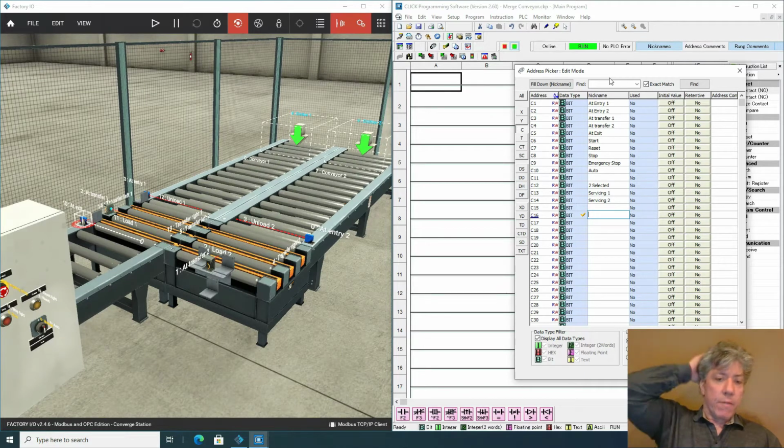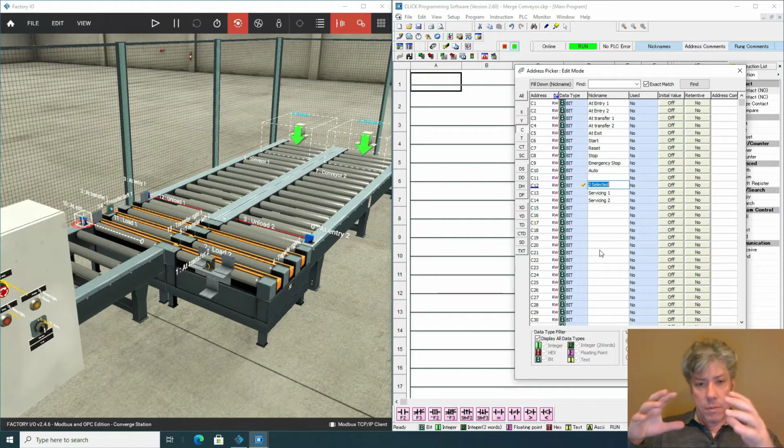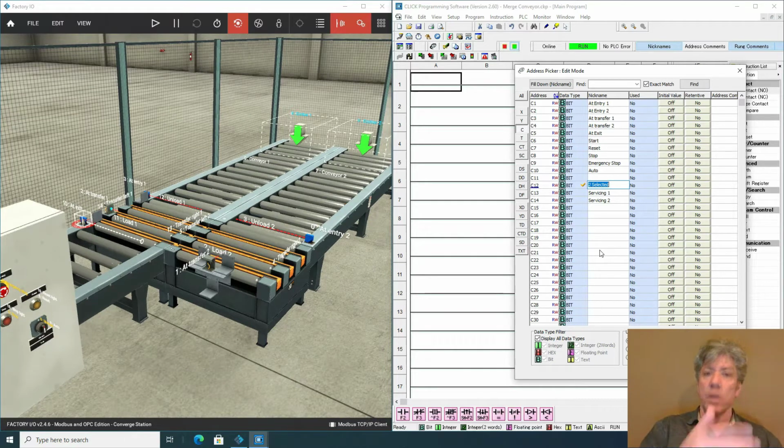Well, to make it fair, you know, it's possible that there could be continuously something that keeps appearing where I've got pallets just waiting to be merged together, and so I've got to make a decision. So what I've done is I've got a bit here that I've defined. I call it toSelected, and the idea is that if this bit is true, then the next pallet that's going to be serviced will come from conveyor 2. If it's false, then the next pallet that will be serviced will come from conveyor 1. So that's just a bit so I can toggle it back and forth and keep track of who went last.